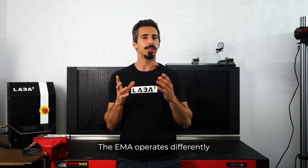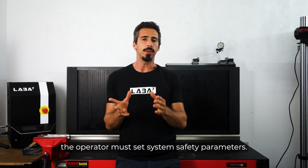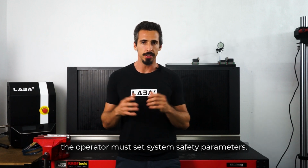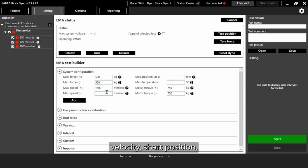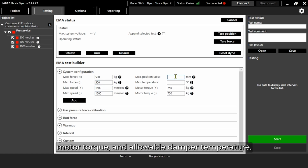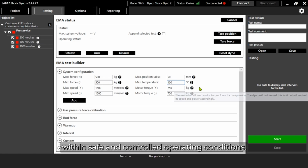The EMA operates differently from Scotch-Yoke dynos, so instead of calibration, the operator must set system safety parameters. In the system configuration panel, you can define limits for maximum force, velocity, shaft position, motor torque, and allowable damper temperature. These limits ensure the test remains within safe and controlled operating conditions.